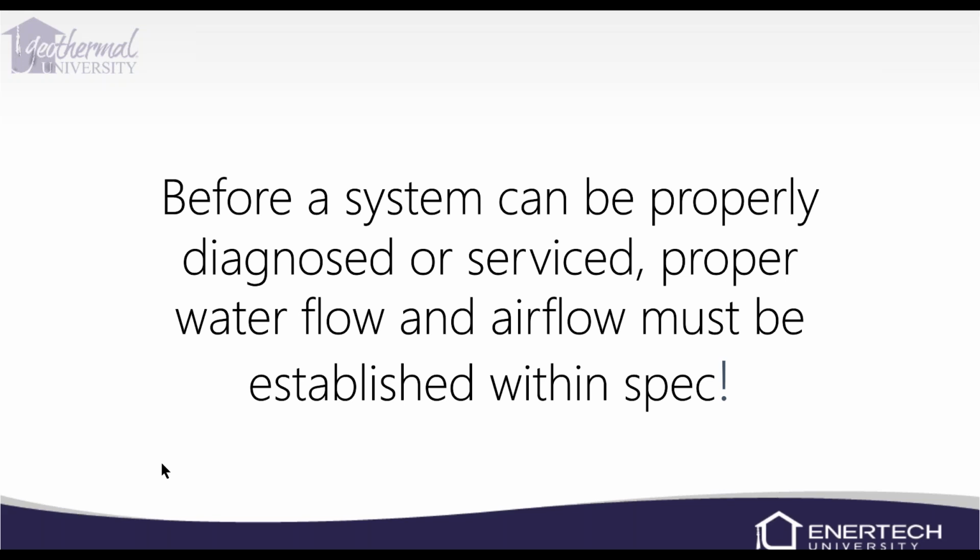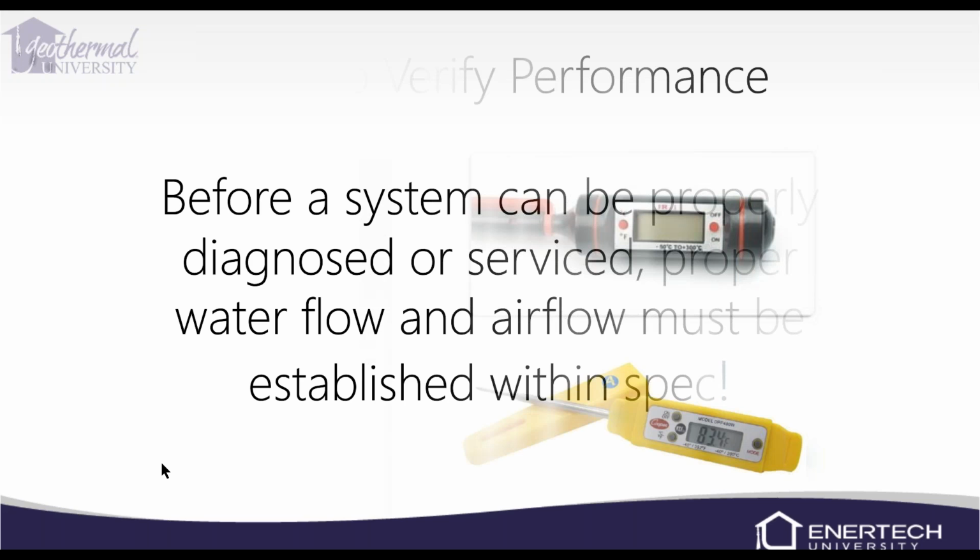With water flow, you shouldn't be able to hear it. If you can hear it, you've got air in the system, and you really can't feel it. So that's why we've got to get pressure drop. But make sure we've got airflow and that we've got power, that the unit is running, that the compressor is operational. And then we can check our water flow. We can check with pressure drop, and that'll start our heat of extraction, heat of rejection calculation.